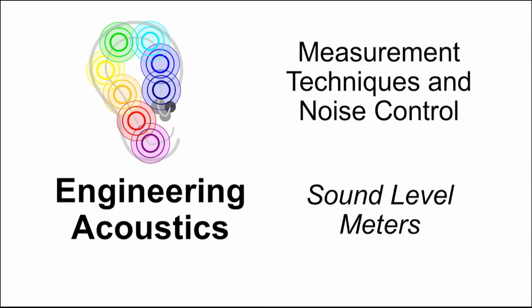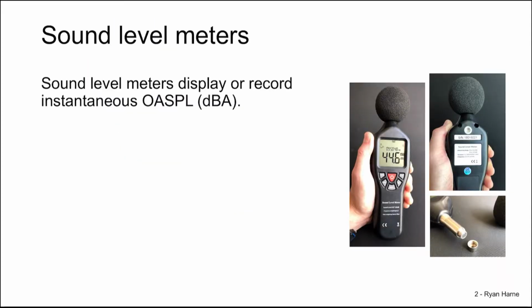In this video, we'll learn about sound level meters, the standard tool to measure overall sound levels in the field. So let's get started. Sound level meters display or record the instantaneous OASPL, the overall sound pressure level. Very often, and without many exceptions, it reports it in dBA.